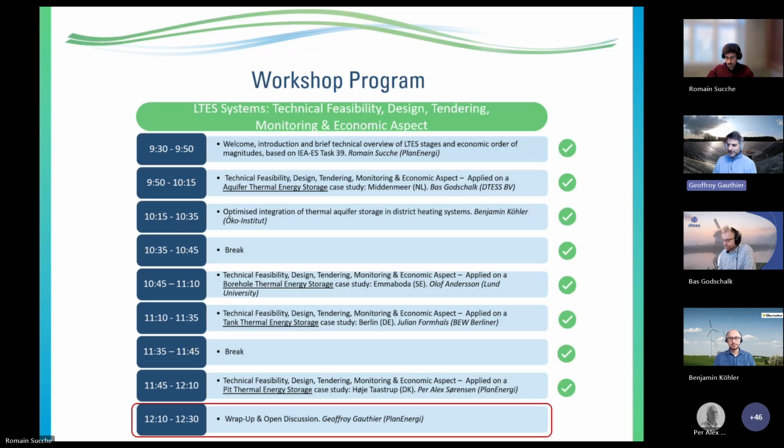Thank you. I think that's a good summary of the different things that should be considered. You also have to remember that a lot of these heating centrals have a bit of ground available, and very often they try to put a tank thermal energy storage on the site. That's also an option, but it is more expensive per volume compared to an aquifer or a pit, or even a borehole thermal energy storage could be an urban alternative as well.